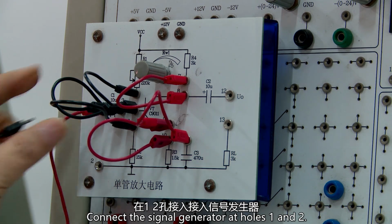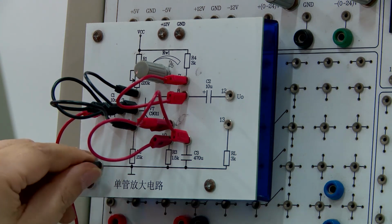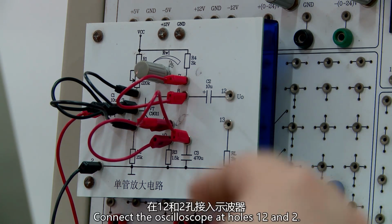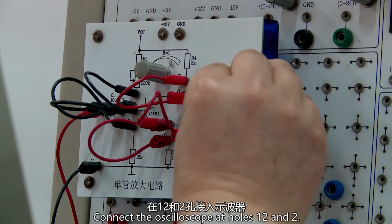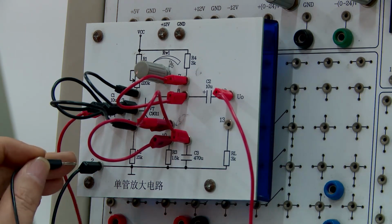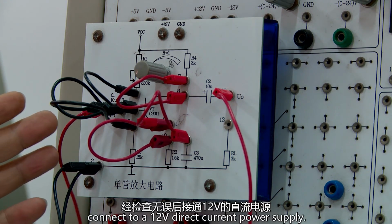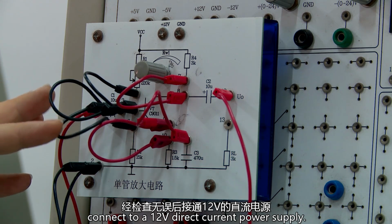Connect the signal generator at holes 1 and 2. Connect the oscilloscope at holes 12 and 2. After checking for errors, connect to a 12V direct current power supply.